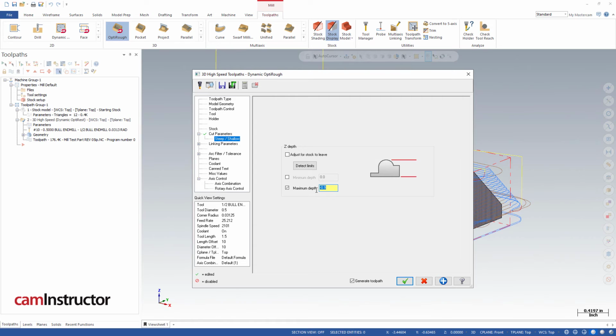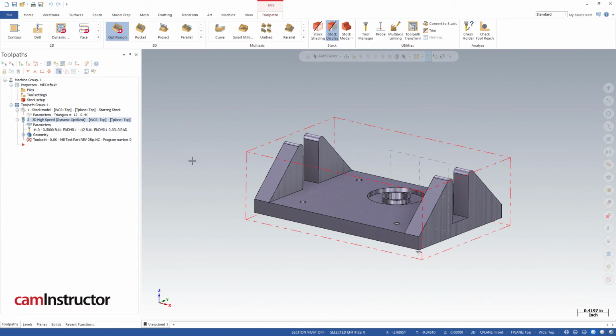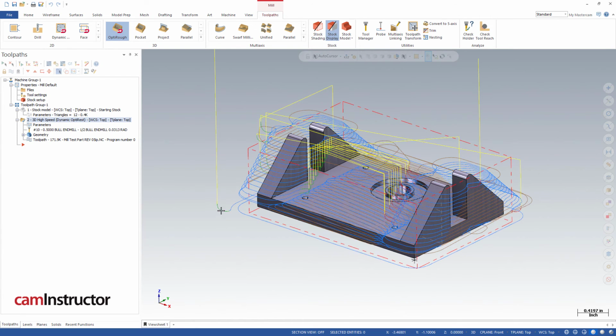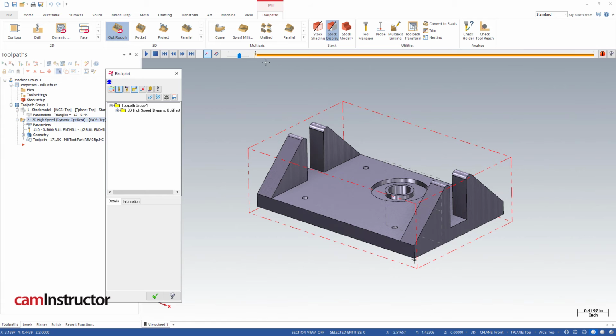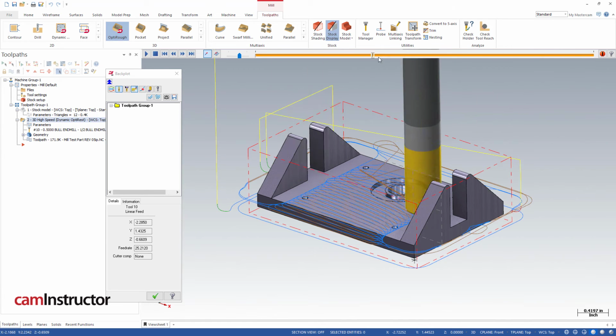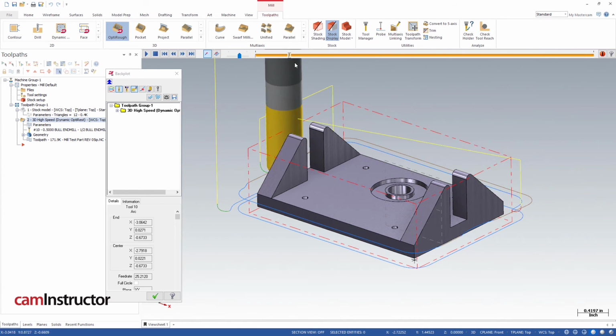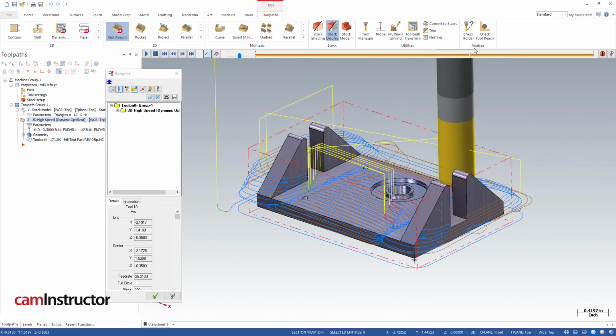This is going to not stop that 1 inch step down at minus 0.9. The toolpath will carry on. I find this is only a problem when both values match. So that should fix that up. Let's green check, rebuild, and now we've got just the one toolpath at the very bottom of the part. So we step down, cut around, and everything else now is a step up.